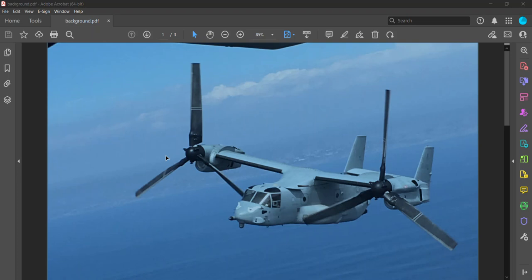So, this is a V-22 Osprey. It's a vertical takeoff and landing aircraft, VTOL. It takes off like a helicopter and flies like an airplane. It can also do rolling takeoffs, so it can similarly take off like an airplane, with the caveat of it can't be in this orientation, right? The blades would hit the ground. So the nacelles are usually at like 70 something degrees when it does that.